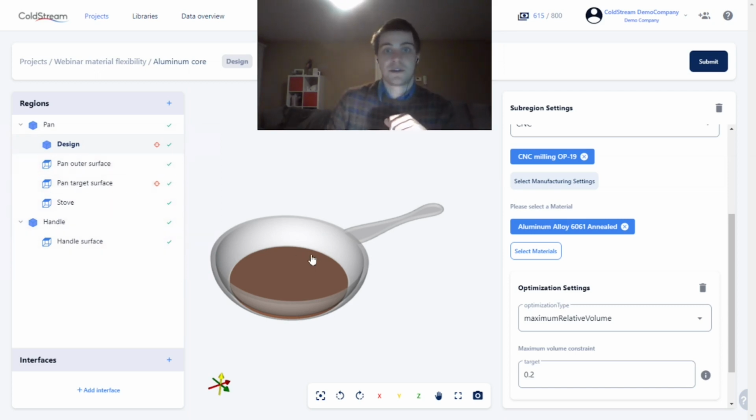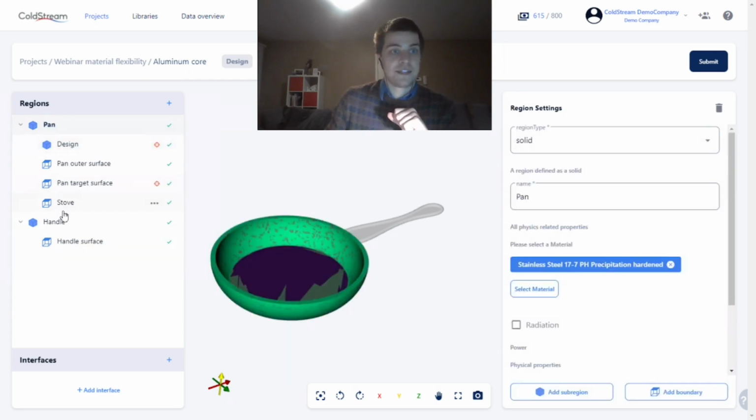You saw me do it in one go, except for the last surface patch. If you want, you can upload all of these entities individually and add subregions and boundary patches or new regions sequentially. But it's easier to do it in one big go, in my opinion, at least.